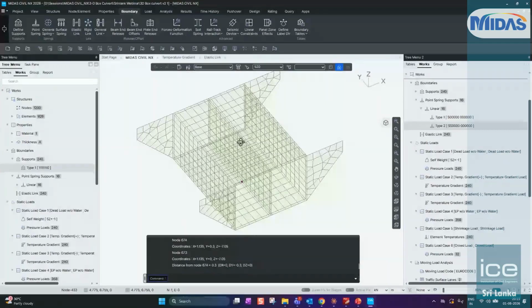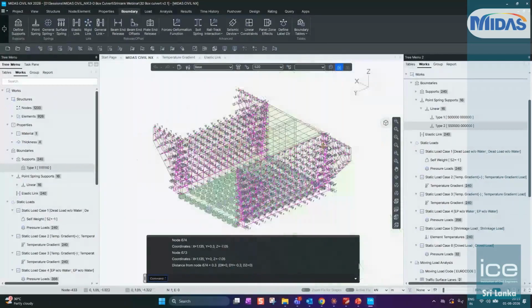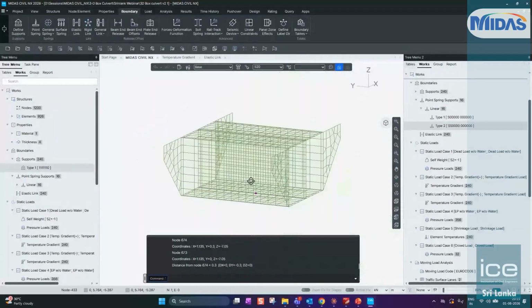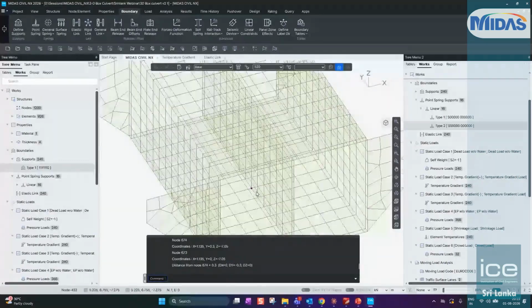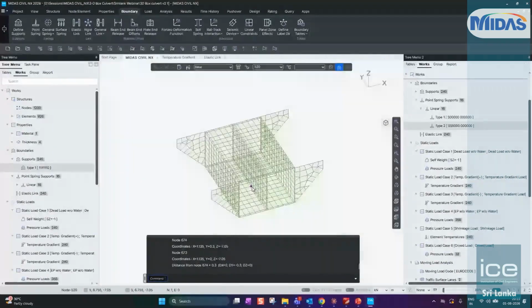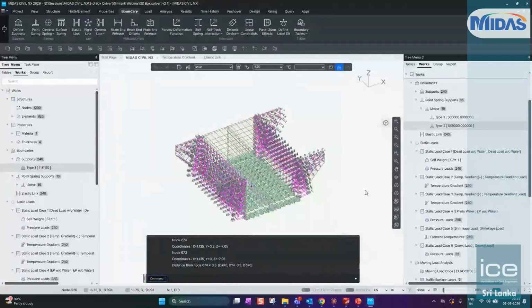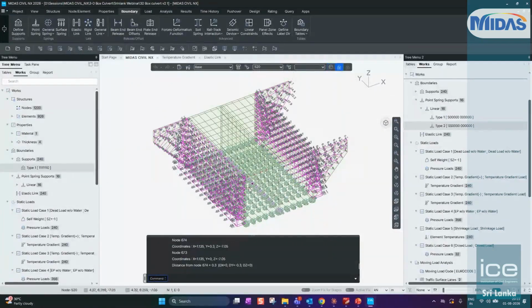The load of soil pressures on these wing walls are equally balanced on the two sides. If the heights were different, then soil pressures would also be different. Then whatever the difference would be, you can see directly in the reaction of this node. Okay. So that is how the supports of the culvert model have been defined. I hope you understand now the reason behind the support assumptions or support assignments.